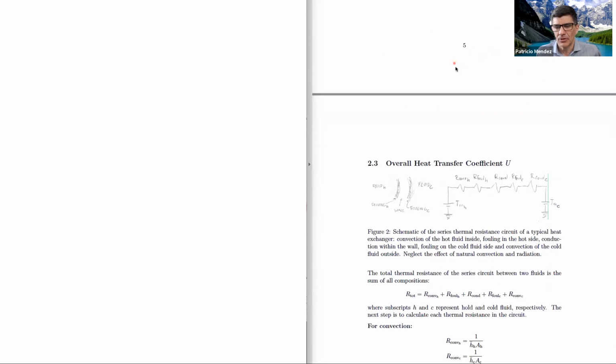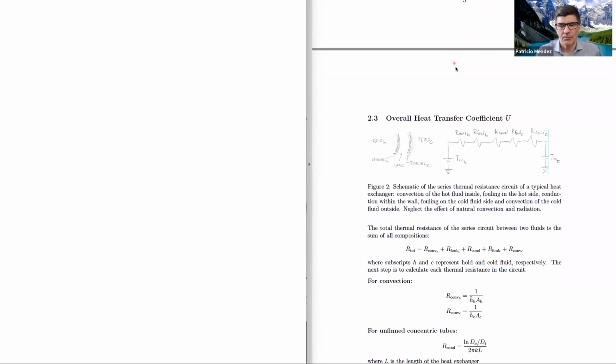And for the overall heat transfer coefficient, you're going to recognize very quickly this equivalent electric circuit for heat transfer through the membrane that separates the two fluids. Can be a pipe, can be a plate, and we don't really care what it is. Can be circular, can be other things. We know how to calculate all those because of our unit on internal flows.